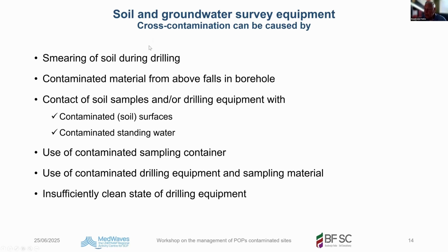That's called smearing. Contaminated material from above falls into your borehole. You stand around your borehole and push soil particles from above into it with your feet. You take your sample and then you have sample material from above.